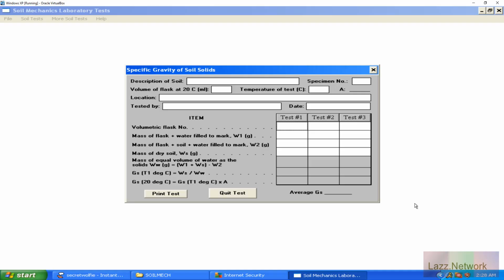Granted, if you go with a bigger size, you want to use more material. Typically, your material size is about 25-ish grams. There's a plus or minus with that. And then for the accuracy of this test, personally, I typically like to report out to the ten thousandths place, but usually this goes out to the thousandths place of the decimal point.